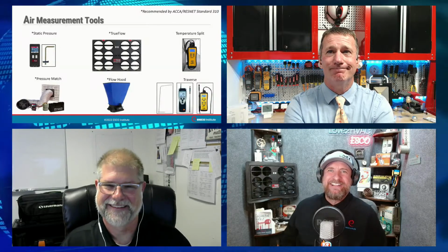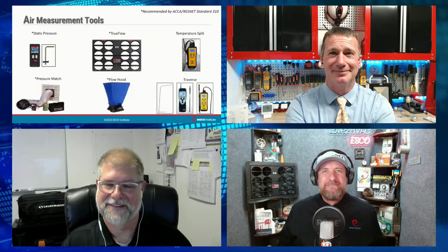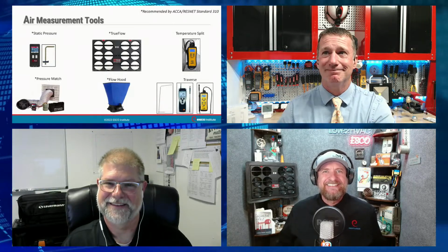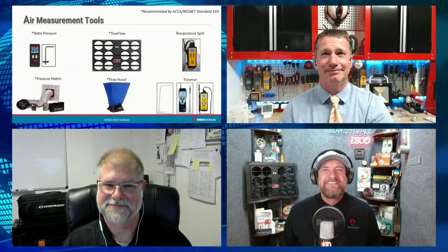I thought I was doing some great ductwork. I thought my ductwork was better than most people around me, but it still wasn't right because I wasn't testing it. It was better, but it still wasn't right. So it was like less wrong. When I started testing properly, I got to see that if I actually do these calculations, I can have properly performing systems. And then I found out I could use smaller systems and have happier customers with lower humidity and proper testing.